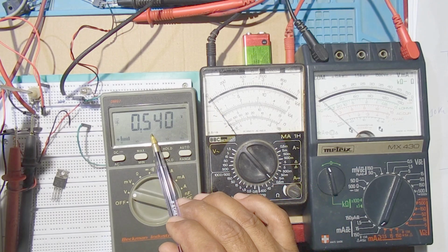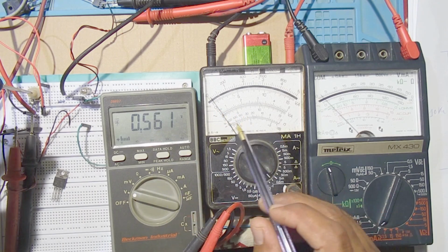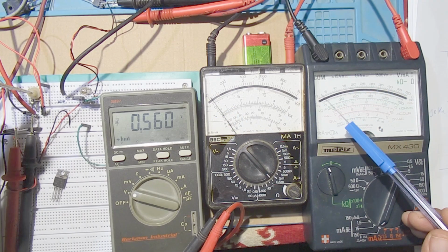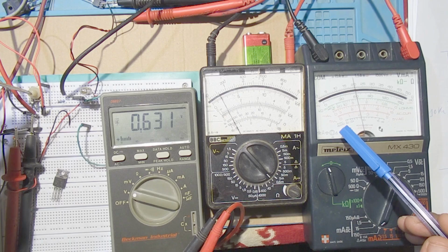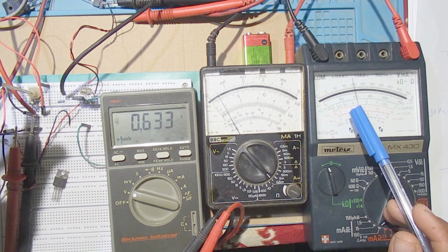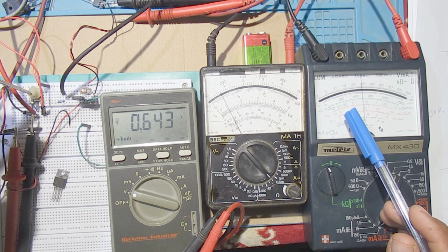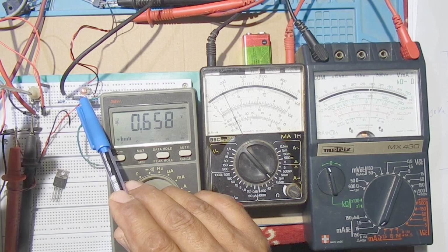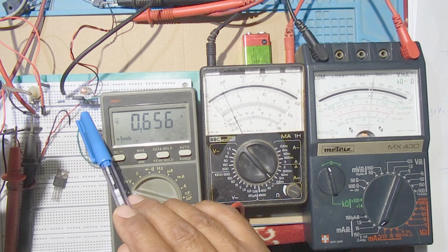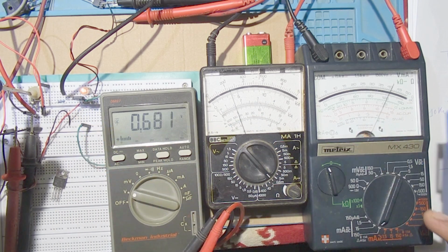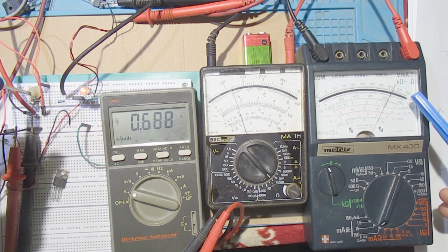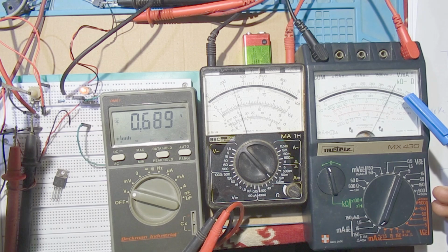After 0.5 volt, the base current will grow, and the collector current will do the same thing. With a little variation of the base current, we have a great variation in the collector current, as you can see. Here we can adjust the brightness of the bulb. The brightness will tell us about the collector current. Here the collector current reaches the maximum value, 120 milliamp.